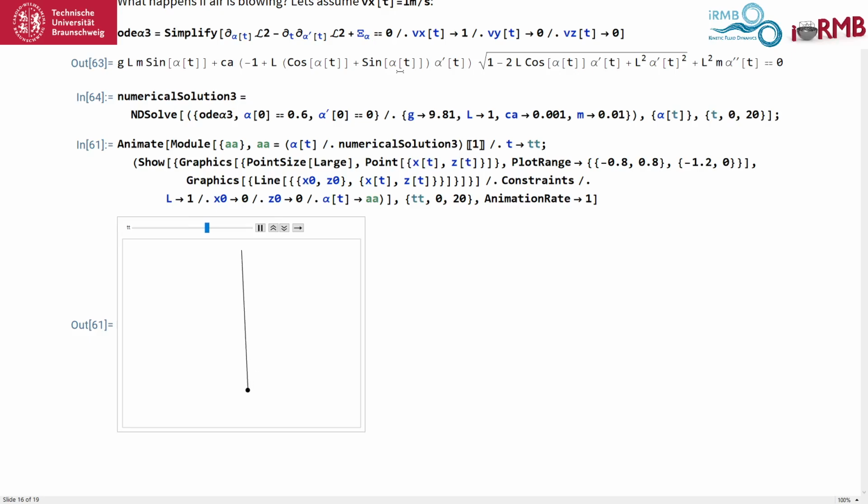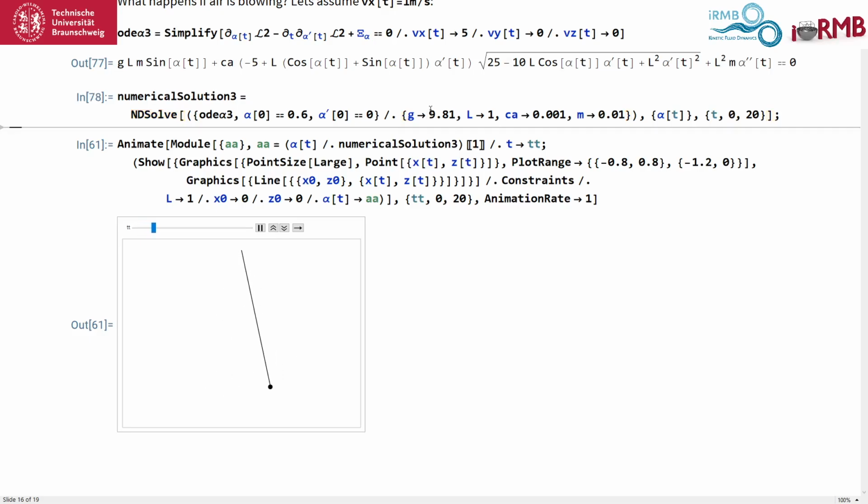Yes, just another example, you can specify a velocity here. So you can add wind. Now I put this to 1, because everything was in meters per second, the SI units, so this would imply 1 meter per second. Can put here a larger number. Now I have to solve it again. And when I solve it again, you see now there's a strong wind blowing.